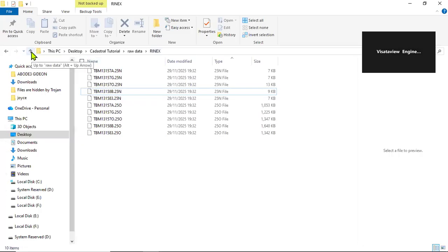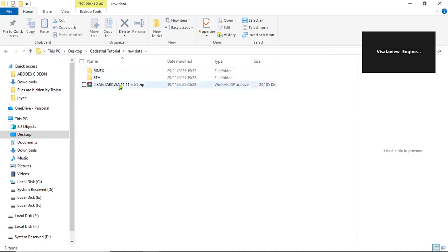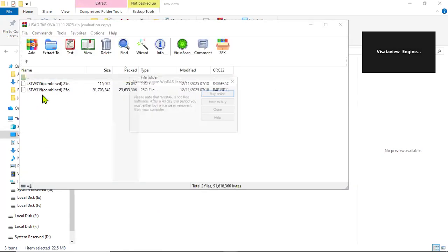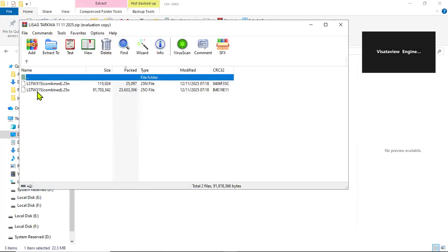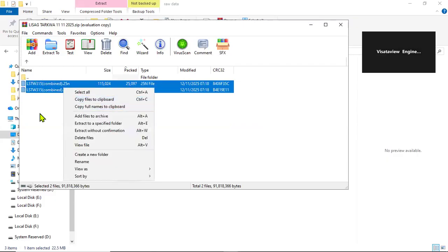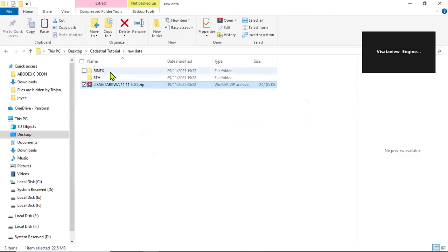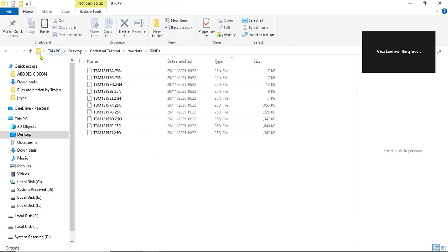So now, with your raw data, you have to add the base or the reference Rinex. When I open the CORS station data, you see that it also has two files, with the N and O extensions. I'll copy it and add it to my Rinex data I've processed.